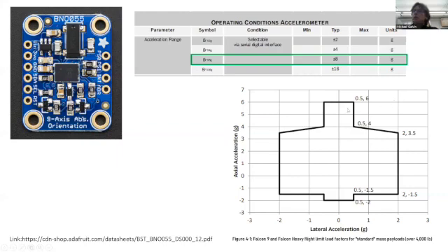And again, we don't really know what the acceleration environment, the G load environment, or the shock environment is going to be for the Blue Shift missions, but we just used a rule of thumb from the Falcon 9 payload and tried to measure up to plus or minus 8 Gs, knowing that we would capture the quasi-static loads of a Falcon 9 payload if we correctly set our measurable range to that level on our BNO 055.